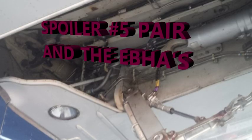And then the spoilers have the electrical backup hydraulic actuator. In particular, there's only the pair spoiler number 5. So that pair has a backup actuator, and that's the electrical backup hydraulic actuator. Otherwise, the other spoilers are using the conventional servo actuators. All right. Okay, and then let's just go a little bit more into that, just to give you a better idea. And if you've seen these at all, just so you know, there's 14 spoilers, since I'm mentioning spoilers right now, and they are paired.